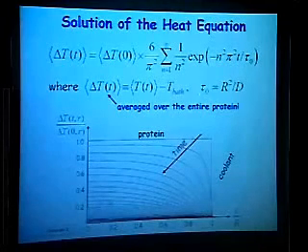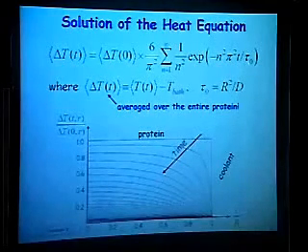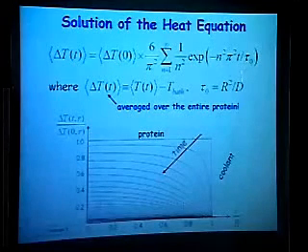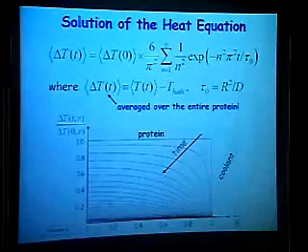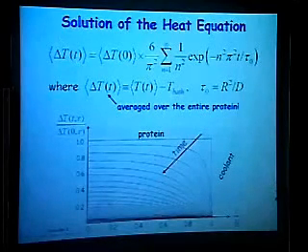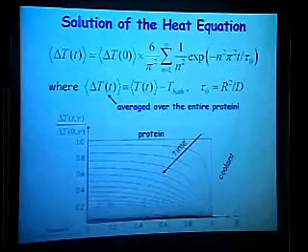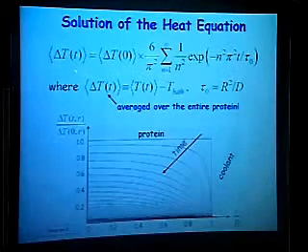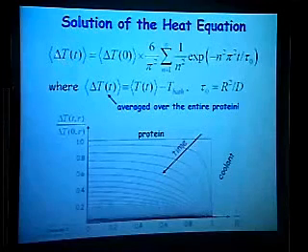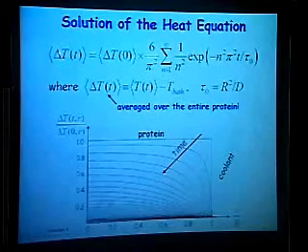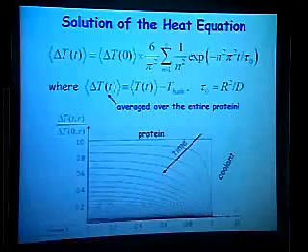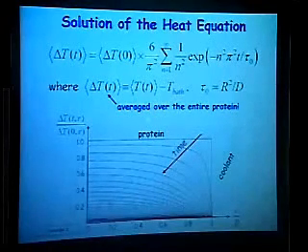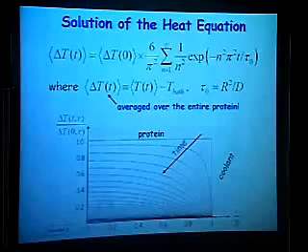And the tau 0, which is r squared over D, appears again here. So you see why this quantity is so important? Because this is actually the time scale on which the temperature difference decays to 0. So this is just another way of writing the cooling process, the temperature change in a system, namely as a distance of the current temperature with respect to the final equilibrium temperature, which coincides with the bath temperature, T bath here.